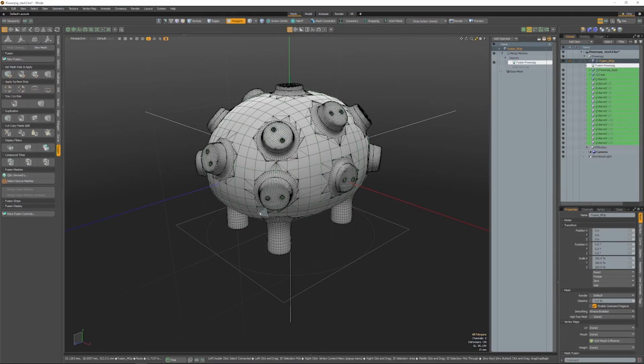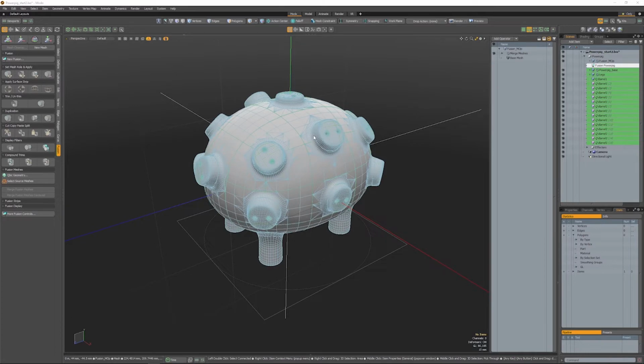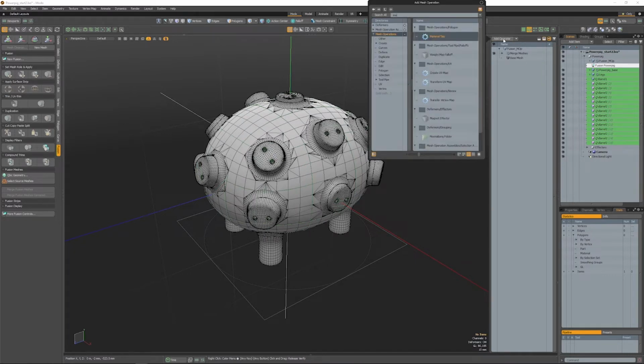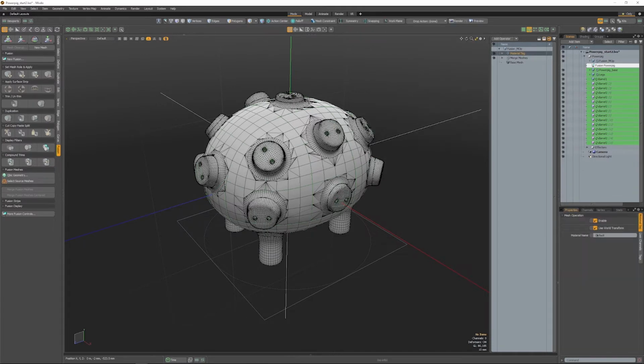So now I only need to apply a procedural material, and then we have all our design procedural. So if you do a design change, everything will update. So for that, I will use this fusion mesh up and apply a material also procedurally. So select it, come here to add operator, and just write matte, and we'll get a material tag. Click it, properties, and change the default name to power peg.